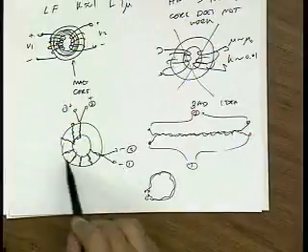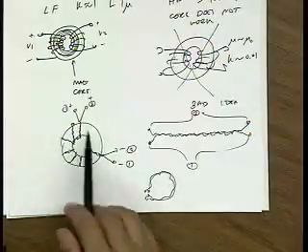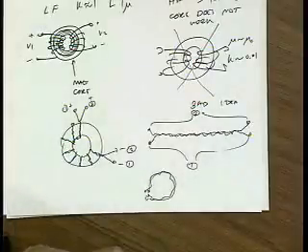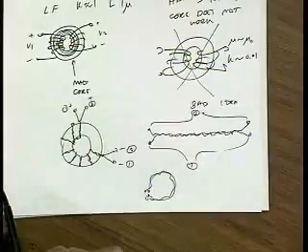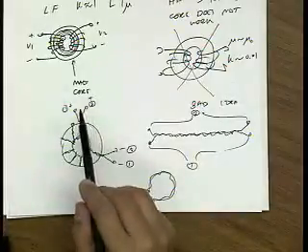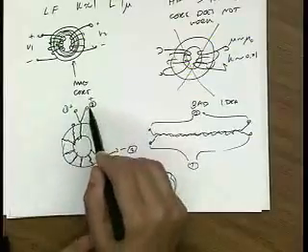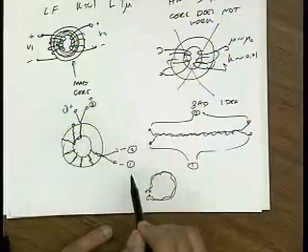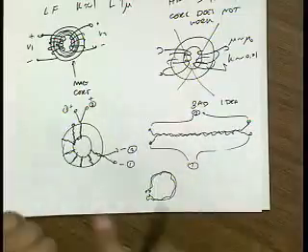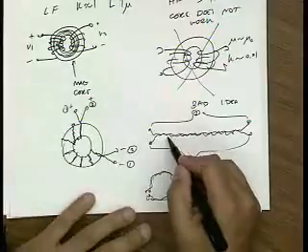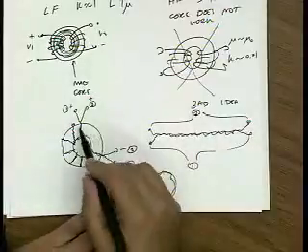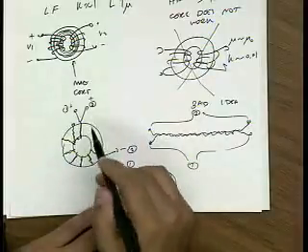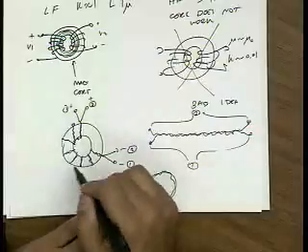So you might ask, why use this core, right? It's not doing anything for you. Well, it turns out that the core is useful because it can reject common mode signals. Let me explain that very briefly. So if I send in a differential signal, that means that current 1 and current 2 are out of phase, then the actual magnetic flux produced by this circuit is very small because these are twisted together, very close together, and the flux area is very small. And so that means that differential signals generate a very small amount of flux.